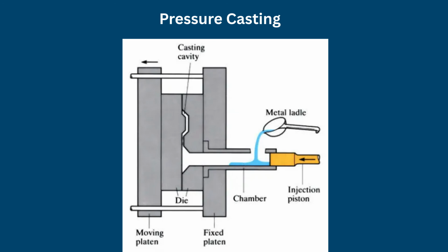Pressure casting combines conventional pouring with elevated external pressure. Following mold filling, the assembly is placed inside a pressure chamber, typically 40 to 80 pounds per square inch, compressing residual air bubbles into microscopic dimensions. This process improves mechanical integrity and surface quality while reducing internal defects.